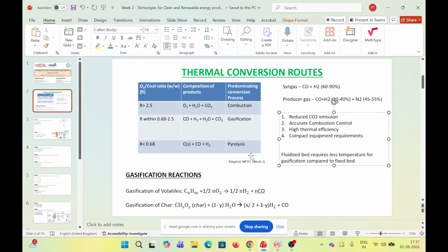Again, after these kinds of gasifier, which are from the conventional perspective, with the recent development in the technologies, we have this plasma gasification process. It's a type of advanced gasification technology where we try to use plasma for the burning of coal to obtain the energy. What actually happens here is that a very high voltage is applied. That high voltage energizes the electrons, which collide and ionize and dissociate and excite the ambient molecules and then create a spark.